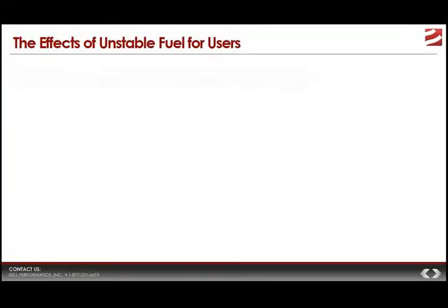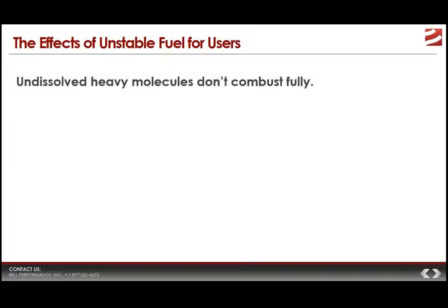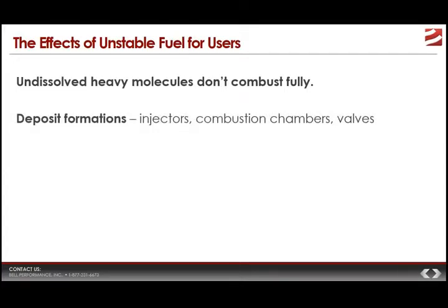Well, because undissolved heavy molecules don't stay dissolved in the fuel, and they're so big, they don't combust fully, they don't burn fully. And because they don't burn fully, there's a couple of things that you'll see. First of all, you're going to get deposit formations. Even before they reach the combustion chamber, that sludge, those heavy molecules, are going to collect in areas like injectors. Of course, in combustion chambers, you're going to get deposits that form there. You're going to get deposits in all sorts of areas in the engine.